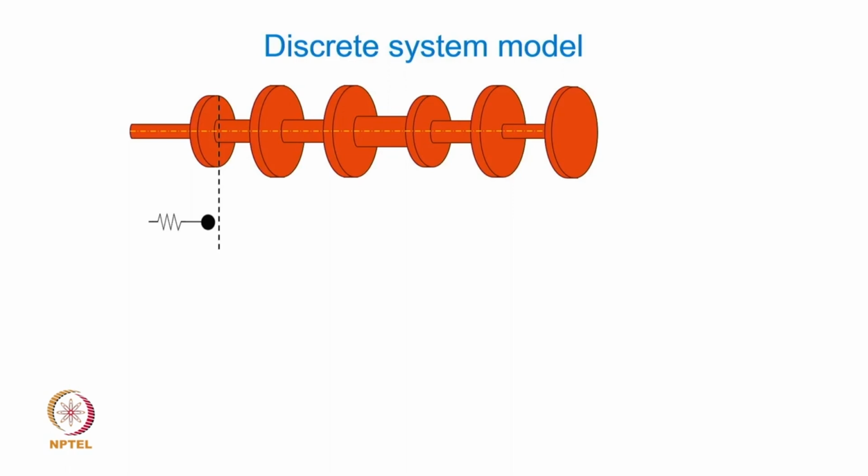So if this segment represents this inertia and this spring, the spring essentially represents the torsional stiffness of the shaft. Okay, that is going to resist the twist in the shaft. So this is the torsional stiffness of the shaft, and obviously when it undergoes torsional vibration, this will represent the polar mass moment of inertia about the axis of the shaft, right. So that is basically how the inertia and stiffness elements together define one particular segment.